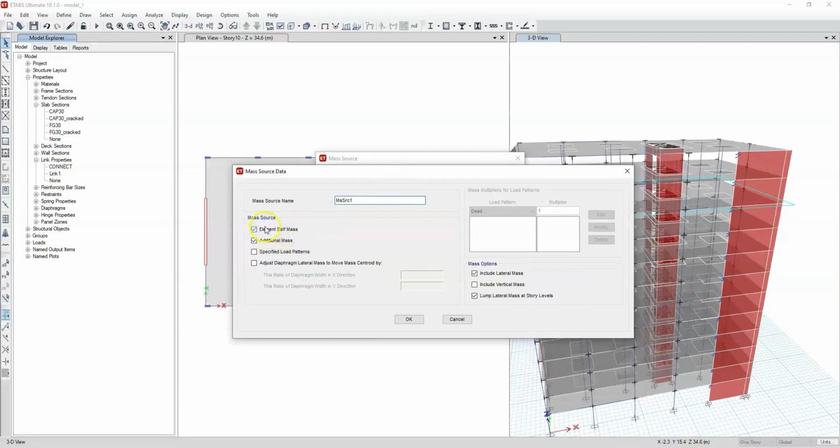The first definition is basically to ensure that the masses can come directly from the masses and materials, and consequently from the elements, because they have an associated material and a volume associated with that material and element. An internal multiplication is performed to define the masses in the element and in the structure. We can also have additional masses, where we manually add masses to the joints. This is very simple, but we can add them manually, though we do not need to in our case.